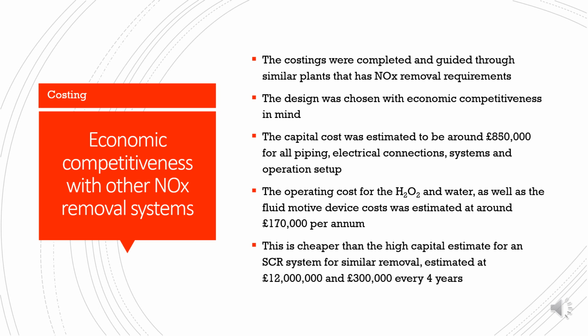And in contrast with other removal systems for NOx, such as SCR, that are commonly used, that was estimated for this plant to be around $12,000 in capital cost, and a running cost of around $300,000 that would be every 4 years for change of catalyst.